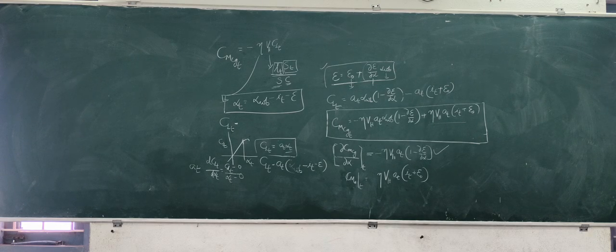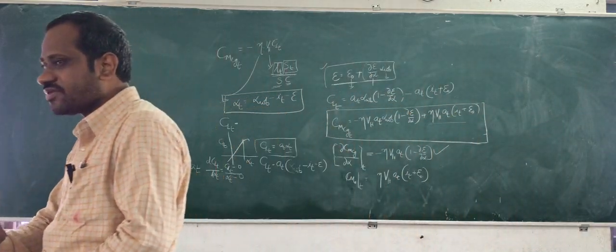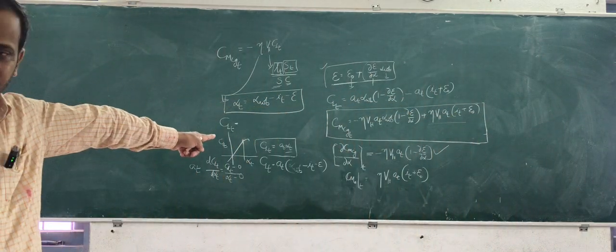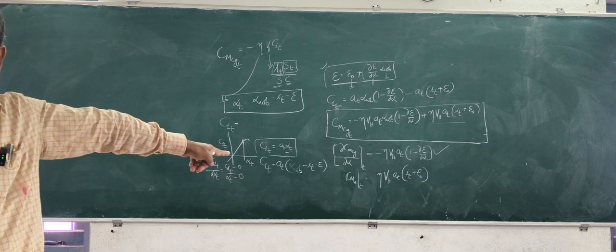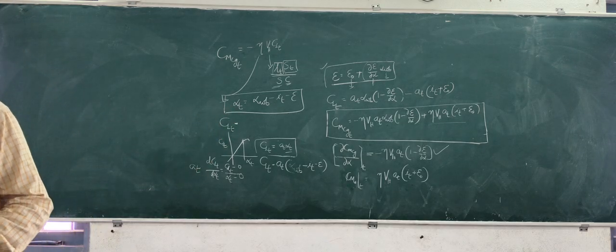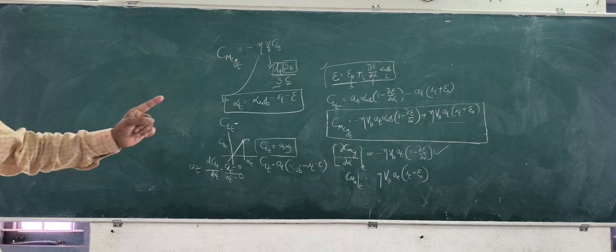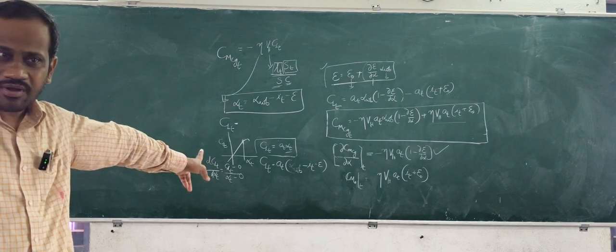If the opposite is set, suppose tail is set above the fuselage reference line, then this will become negative. But by the diagram, IT is positive. Downward setting angle of the tail is considered as positive in our derivation. So IT is positive according to us. So CM naught is positive.